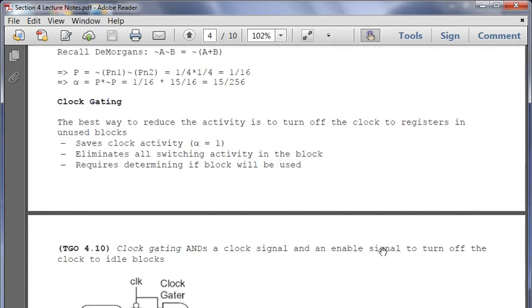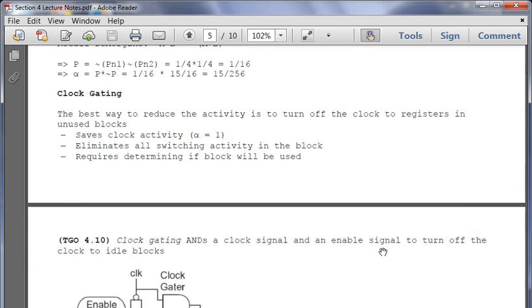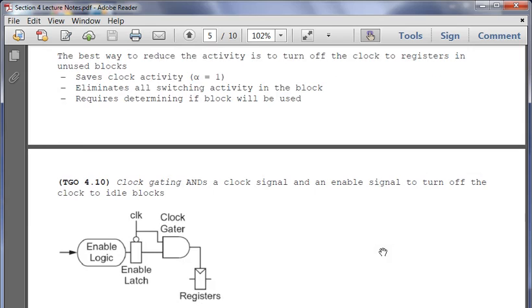What's the typical VDD that they use? It depends on the supply voltage. For example, 0.25 micron was 3.3 volts, and when you get down to 90 nanometers, that's like 1.8 volts, and then when you get down to 22 nanometers, it's 0.85 volts.